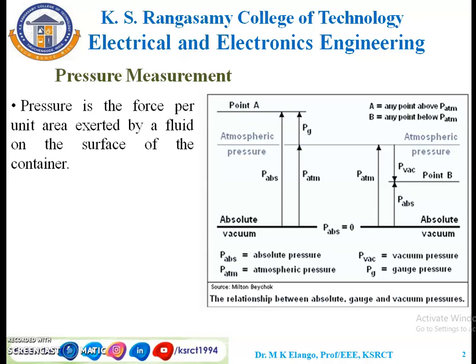The pressure measured by the instrument is called gauge pressure, and the measurement process is called the gauge measurement process. Gauge pressure is zero-referenced against the ambient air pressure, so it is equal to absolute pressure minus atmospheric pressure. Negative signs we generally omit.